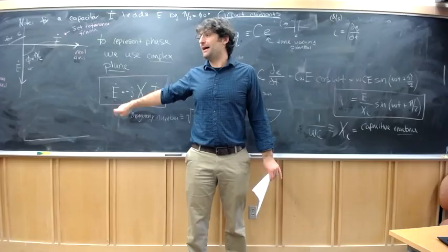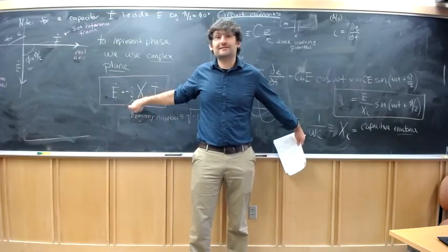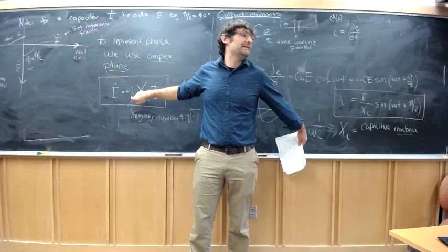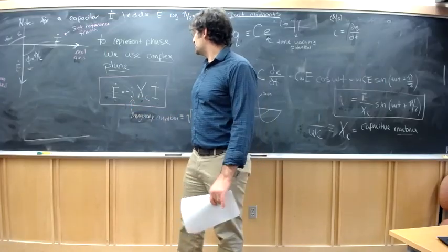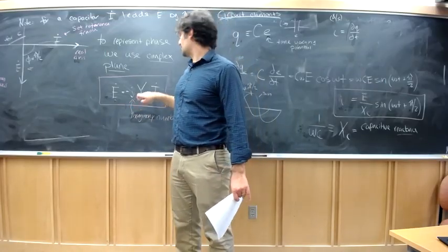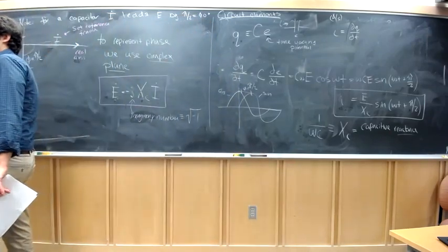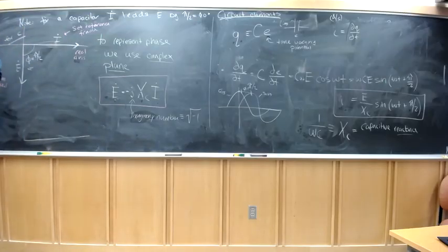This is Ohm's law for a capacitor. Your effective resistance, impedance actually, is the impedance of a capacitor. Impedance is the AC equivalent of resistance. It is frequency dependent. You also have to represent that the current and the voltage are not in phase. And the way we do that is current is imaginary, and on the complex plane, that means a phase shift of 90 degrees, and we're all done. It's all taken care of, right?